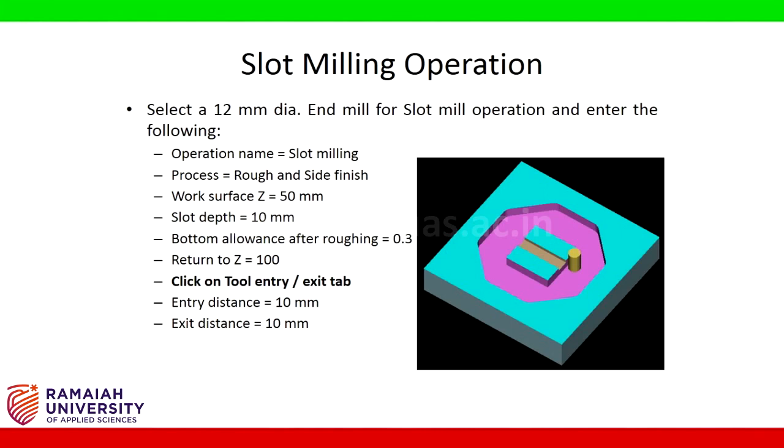Click on the tool entry or exit tab. Entry distance equal to 10 mm, exit distance equal to 10 mm. Click on OK and save the file.